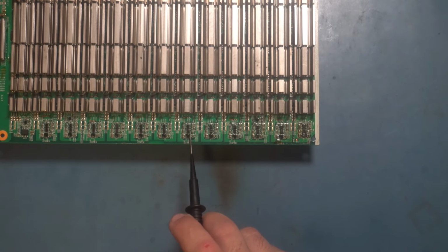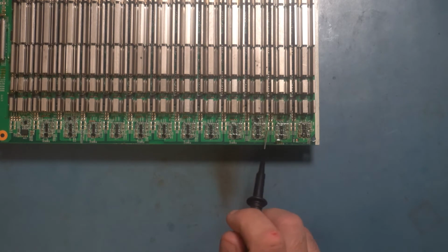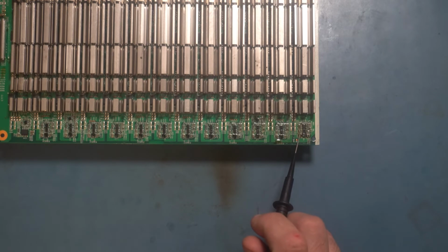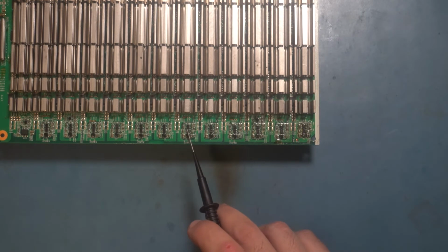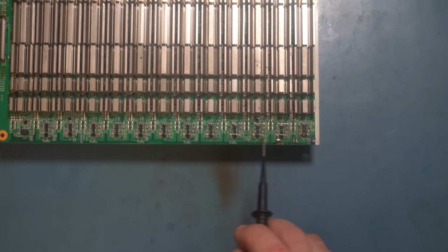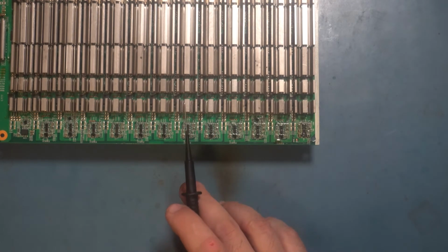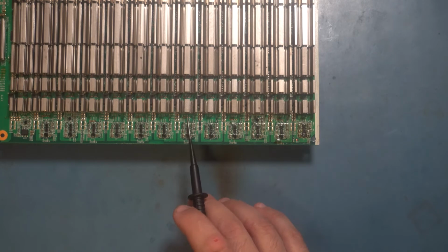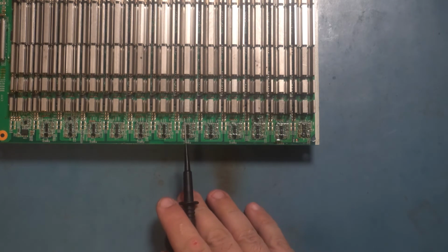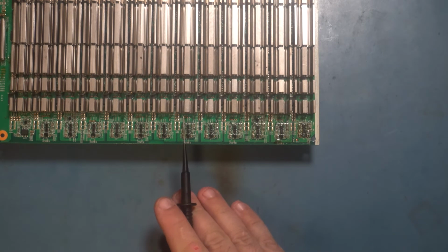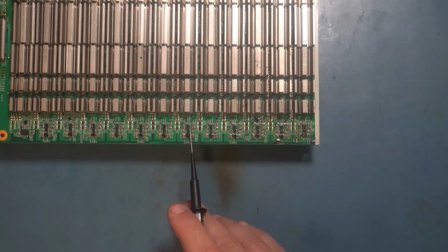If they end up seeing 1.8 volt relative to that first domain, then for them that's a negative value, right? That's lower in voltage than even their ground. So that wouldn't make any sense. All that to say that each domain needs to have some sort of voltage used as input to those LDOs in order for them to generate 1.8 volt.